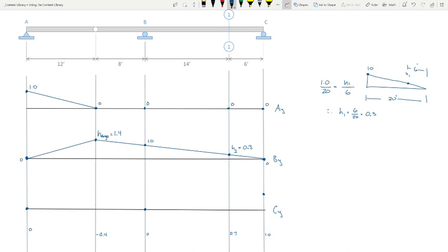Two solid pieces. I remove from the structure the ability to resist the reaction at C. Lift that up. And what do we have? Pivots around this, changes direction at the hinge. We go down, back up. The influence line for the reaction at C looks like this.